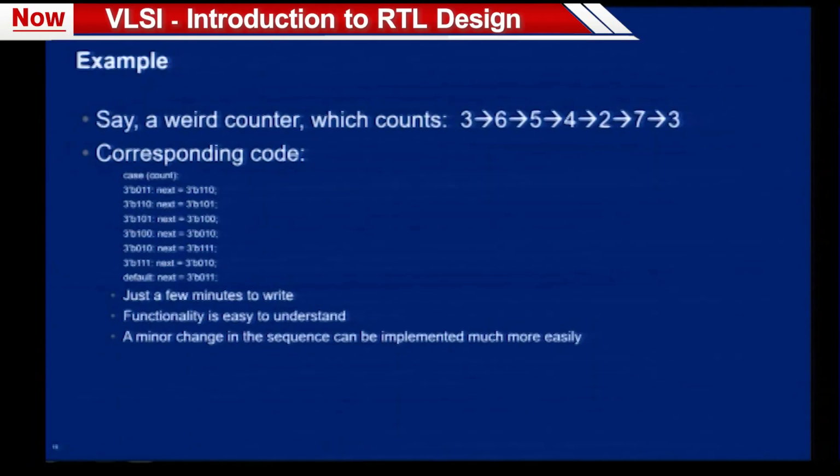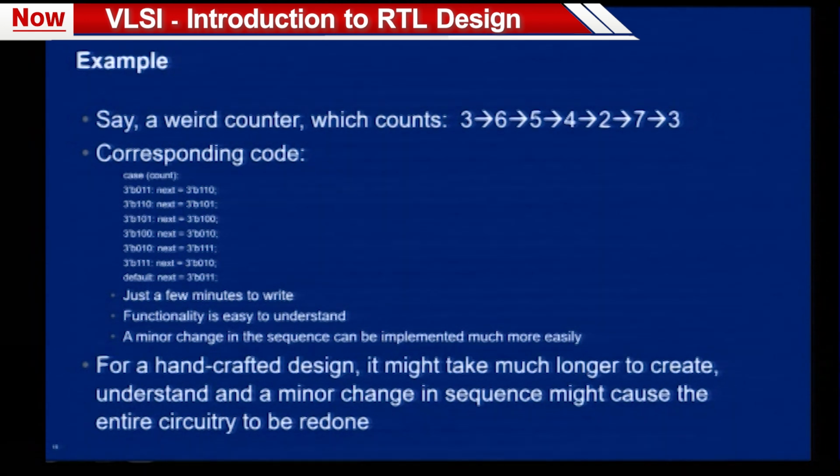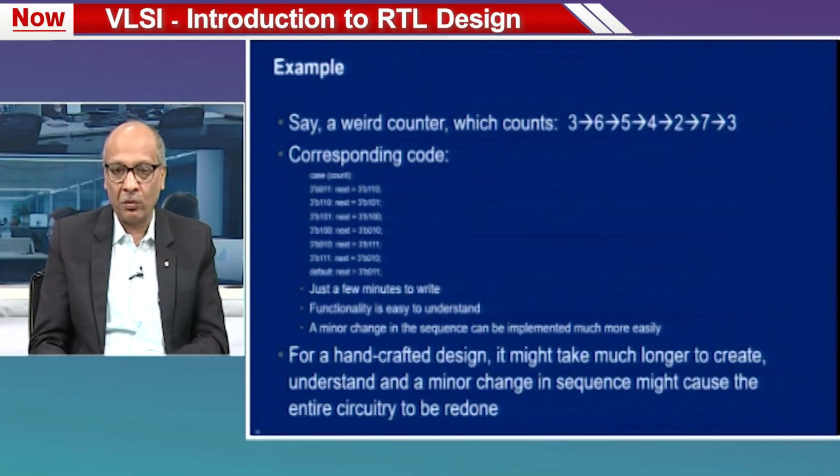So, if you want to make a minor change in the sequence of this counter, you can implement that much more easily compared to a digital design. So, this is at least one very major advantage of RTL based design, that you can write the code very fast and then use a synthesis tool to realize the gate level netlist. The code is easy to understand. The code is easy to modify. If you are making a minor change to the desired logic, the code is very easy to modify also.